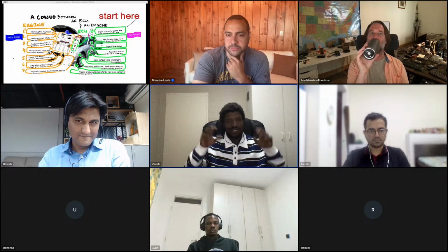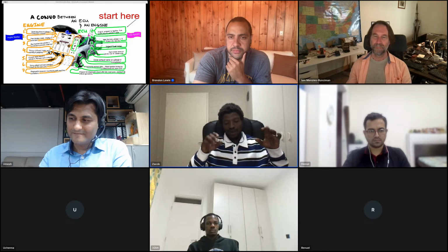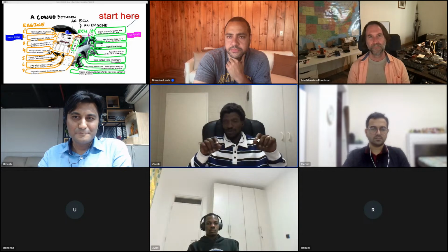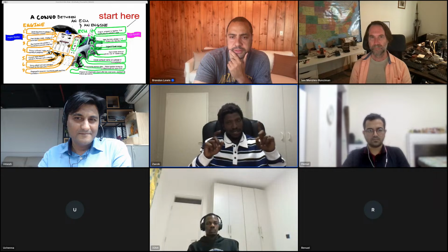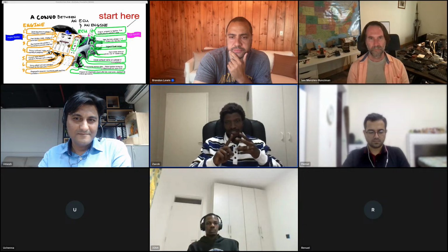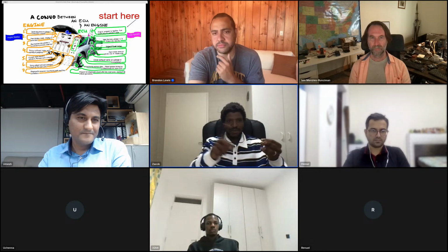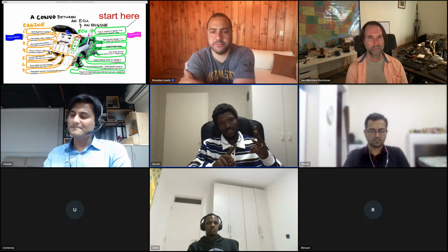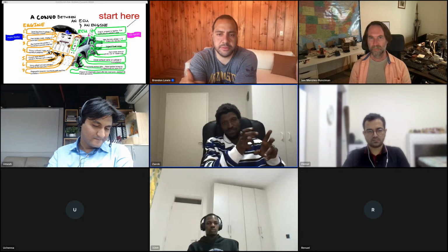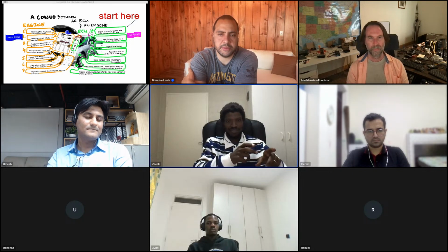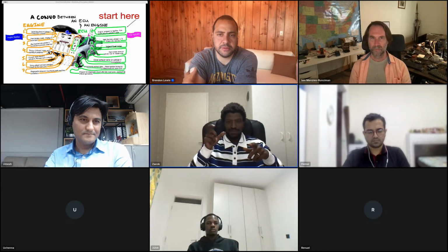So message queuing is when you need to get information from three sensors. You need temperature, you need humidity, and then, let's make another random one, some infrared thing. Three little sensors. The amount of information you're getting differs: one gives you 16-bit, one gives you 8-bit, one gives you 24-bit.